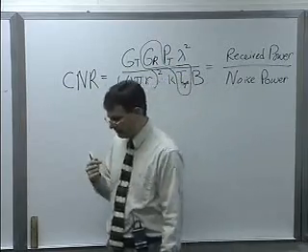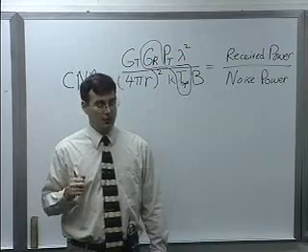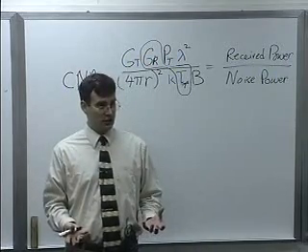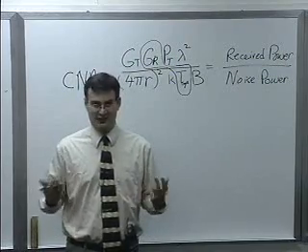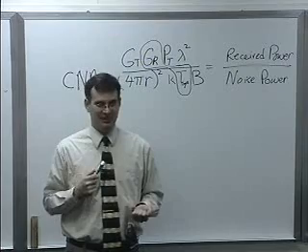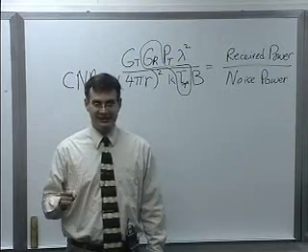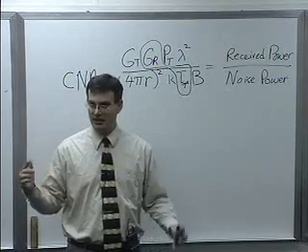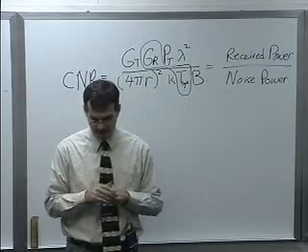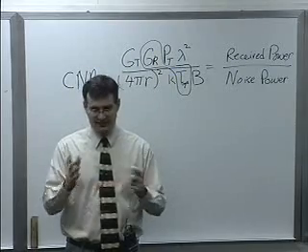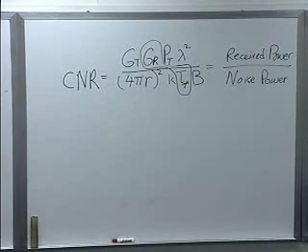And then when we're done that, hopefully we'll have some time to get into Doppler shifting, which is another channel effect in our satellite system, and one that we don't normally worry about for terrestrial systems because stuff doesn't move that fast. But we're going to see with a couple of examples that in satellite communications you can actually get a significant Doppler shift in the data that you're actually sending. So that's sort of the outline for today's lecture.